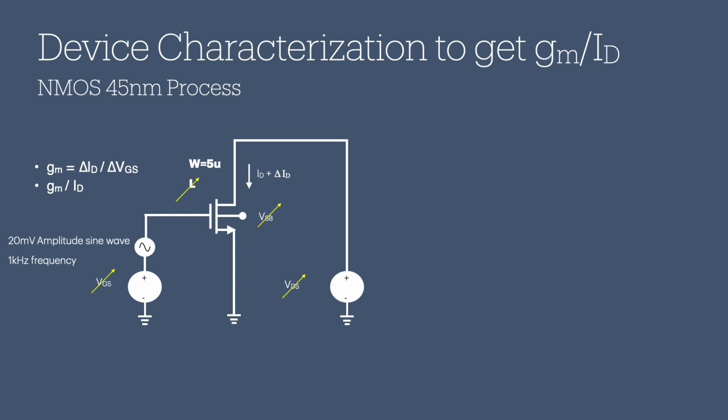By sweeping the channel length L, the VSB, VDS, and VGS, we are able to produce a multidimensional plot. To simplify our discussion, we will only be sweeping the parameters VGS and VDS in our LTspice simulation. We will leave it as an exercise for the student to sweep L and VSB.